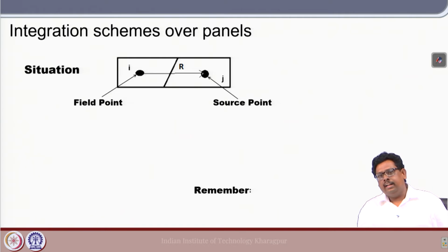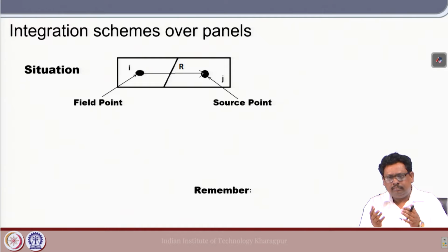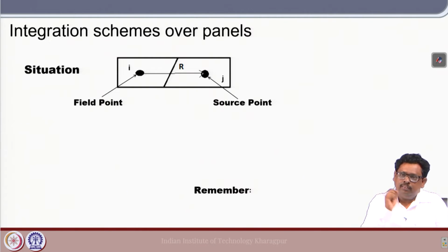In case of a Rankine panel method, that is the whole free surface plus body, and in case of this Wamit type solution, in our case it is the body. So, it means that I discretize the body, and then we need to perform the integration over the body. I just take one arbitrary panel j, then j runs from 1 to n.